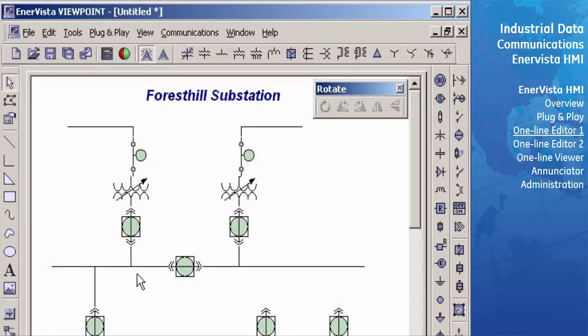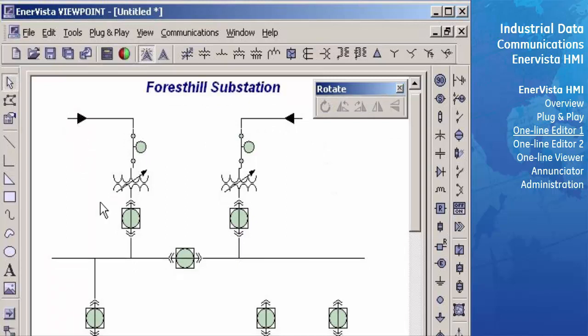Additional elements such as arrows can be added as necessary. In this case, we add the arrows to follow electrical guidelines. Click on the arrow icon and then click on the work area. The arrow should now appear. You can resize the arrow by clicking on it and then dragging the corner of it to shrink the size. You can create the arrows for the other parts of the schema by using the copy and drag techniques you learned earlier. Rotate arrows as necessary. To make things easier, you can always select several components together to be duplicated.